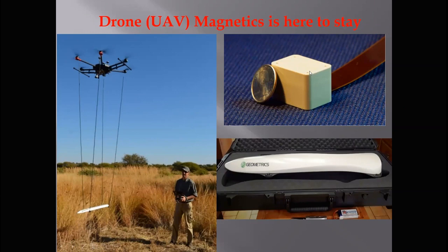We can have one at one orientation and one at another orientation, and therefore when we flip the drone around, we can pick up the magnetic field more accurately with one or the other. We can take an average, or we can say we've got a better result from this drone in that orientation. Or you can just have them both in the same orientation. We've got no issues with the field inclination, and you can either average them or use one as a backup.